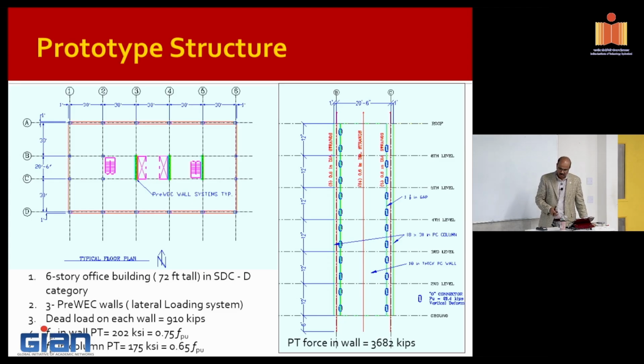Now, you don't want to take those walls and put couplers and make them rigid, because then they will be restraining the movement and they will start dissipating, or they will start to resist lateral load. That's not what you want to do. So it's easy to create a pin system for a wall structure. If you run unbonded post-tensioning and let it rock, depending on the location of the post-tensioning, you can make it a pin-type connection. Does that make sense? Yes? Okay, I don't want them to lose.